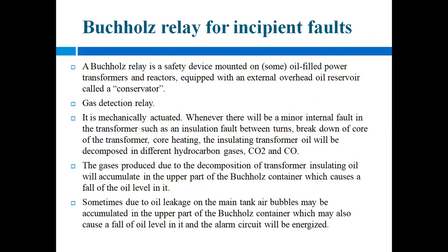Then next is the Buchholz relay. This is for incipient fault. Incipient means these are the slowly developing faults in the transformers. So this Buchholz relay is important here. It can be asked in examination also. So it is a gas actuated relay mainly.